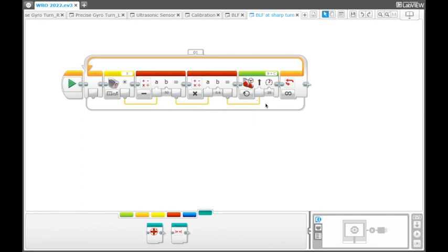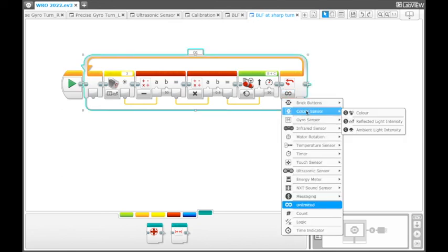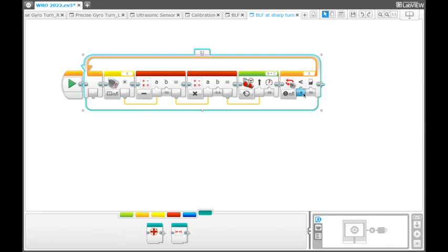for that you have to do a small change. You just need to change this unlimited to the color sensor reflected light intensity, where you can give greater than or equal to maybe 90. I am giving this 90 value because if the robot is following the black line, your color sensor might be getting values around 50, 60 or somewhere near that.